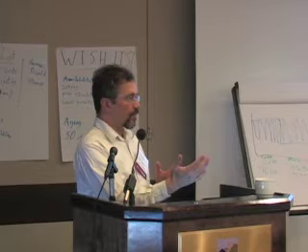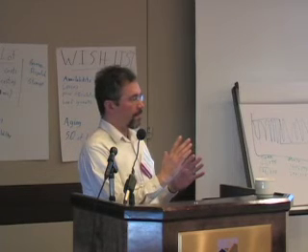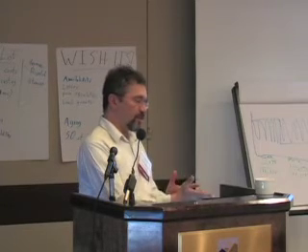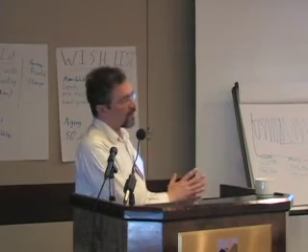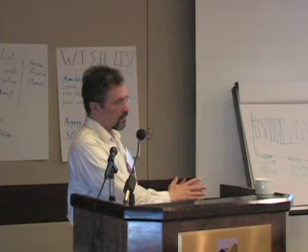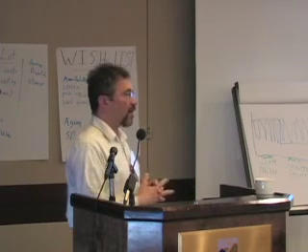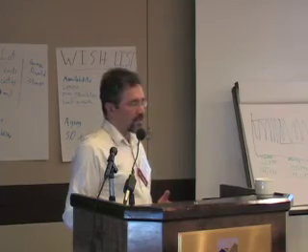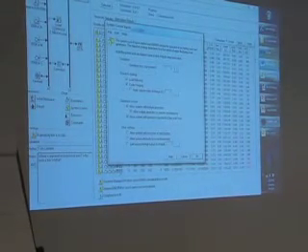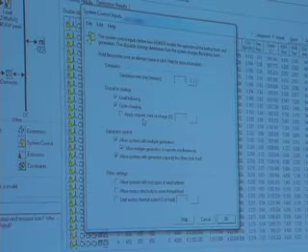And so the simplest approach is to say, if you choose load following, the diesel's never going to charge the battery. The battery is only going to be used to absorb excess renewables. Now, that's not necessarily always optimal. So cycle charging instead says, if you need to bring on the diesel because the batteries can't meet the load, then you should charge the batteries. Sounds reasonable.